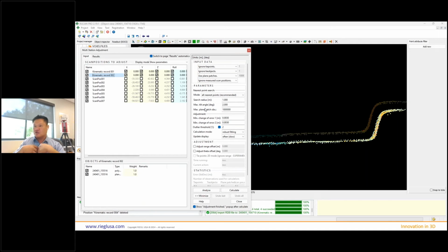Other surveys too as well that I'm not sure about. I'm not a surveyor. But if you were doing an alpha survey, you don't even need control. You can just use RTK, and that's typically good enough for deliverable quality, geospatial quality for alpha surveys. RTK GPS is good enough.